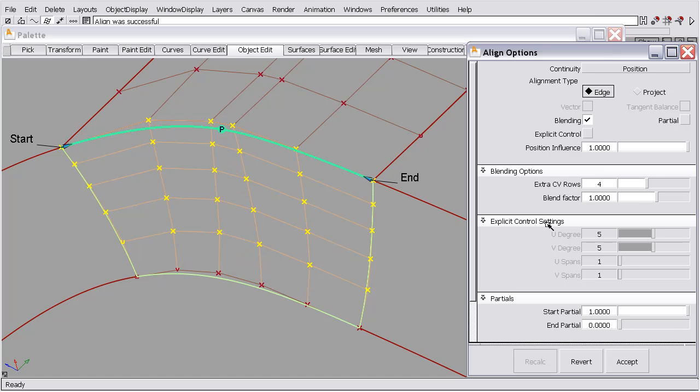So it's not a distance, it's just a tapering value. So as it moves away from the base point where the base edge was aligned, it tapers off. Okay? 1 again is tapering. 0 is no taper, the same movement. So if we went minus 0.5, that's move a distance in addition to what the base point moved.